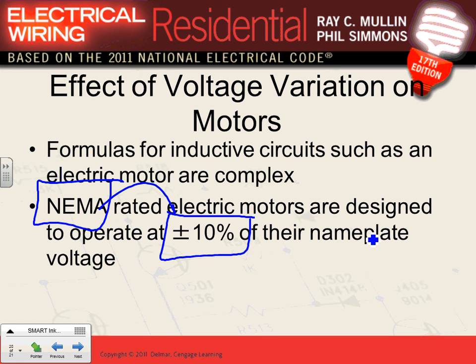If I have a water heater or a pump, and the nominal voltage is 240 volt, single phase. Okay, so if I go 10% higher, what's 10% times 240? Anybody have a calculator? So 1.1 times 240, 264. In this case, I'll get 264 volt, okay?